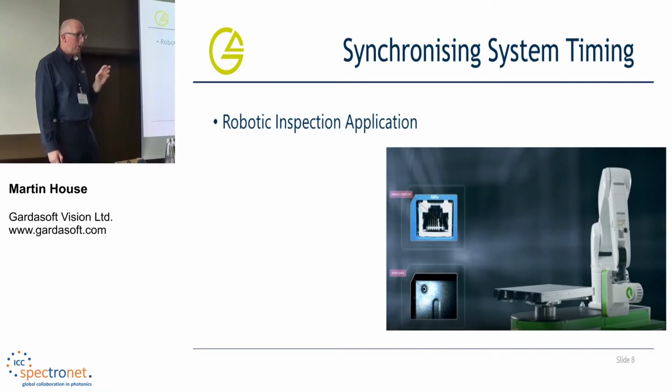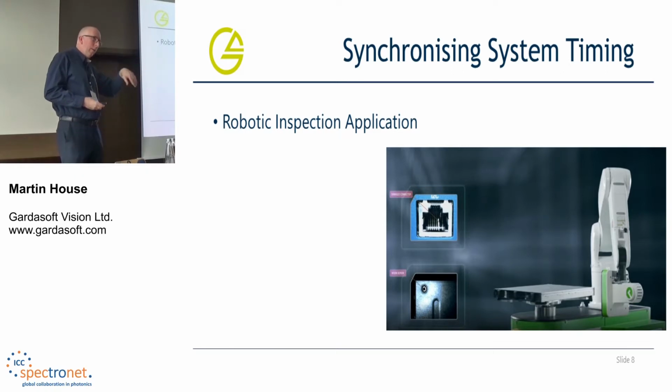So here they've developed an inspection solution around a robot, and they're using a timing control to synchronize the robotic movement. They also have their product on a turntable, and it's synchronizing the illumination with the robot motion and the camera grabbing and the light pulsing. And it makes for a very nice, tight solution.